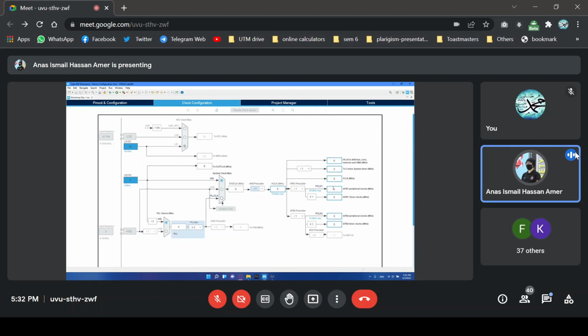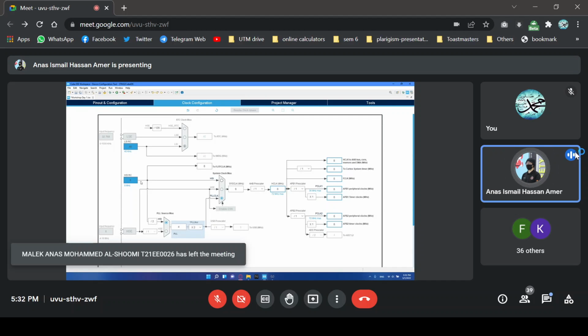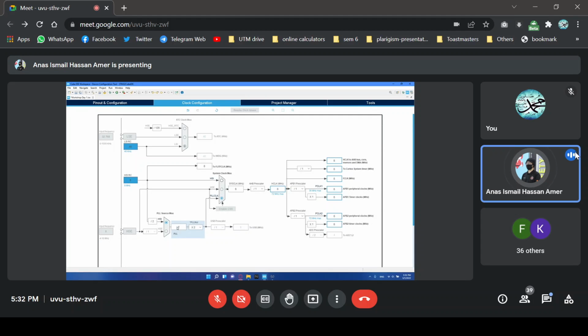Generally, we need our microcontroller to be running at the fastest speed. So we need to choose the PLL clock, this one, since it has a multiplier option. So what this does is just multiplies the internal oscillator. The internal oscillator passes through this divider, so it gets divided by 2, so it's now 4. And then we get to multiply it by a certain number. Let's choose the most, which is 16. And then you'll notice that now we're outputting 64. But this is already over the max, which is 36. So we can divide this by 2, achieve 32.